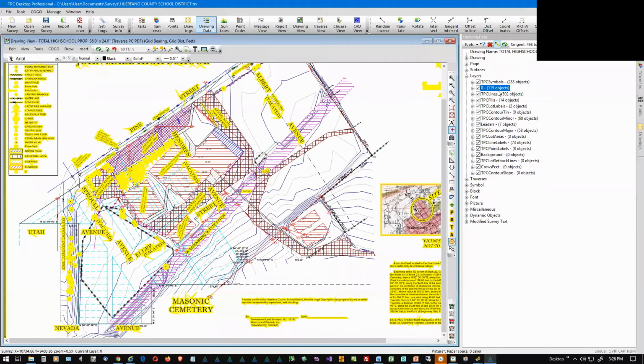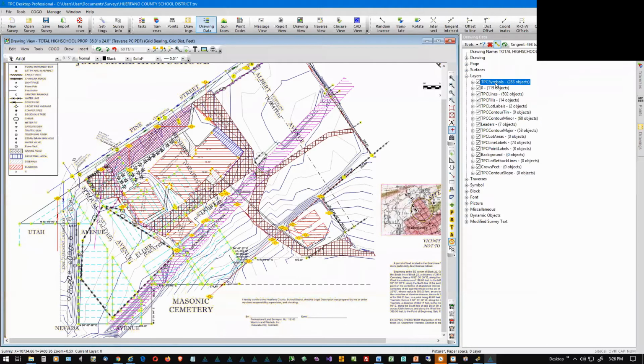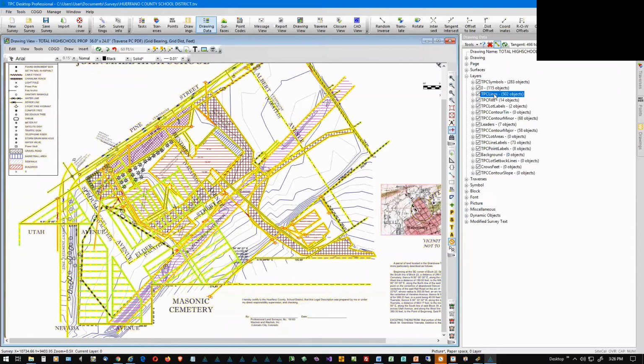Okay, now you are seeing another advantage of the delineate tool. Right now I have clicked on the 0 layer overall. So what you're seeing highlighted now is every object on the 0 layer. I could do this with every layer. So now every traverse symbol is highlighted on the drawing. I could do traverse lines, etc., etc. So you can find out what's what very easily by simply delineating an entire layer or delineating an individual object.